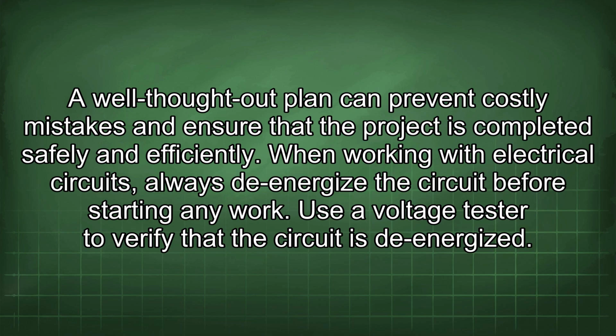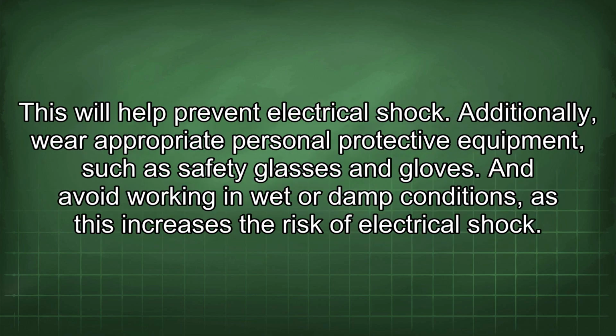Use a voltage tester to verify that the circuit is de-energized. This will help prevent electrical shock. Additionally, wear appropriate personal protective equipment such as safety glasses and gloves. And avoid working in wet or damp conditions, as this increases the risk of electrical shock.